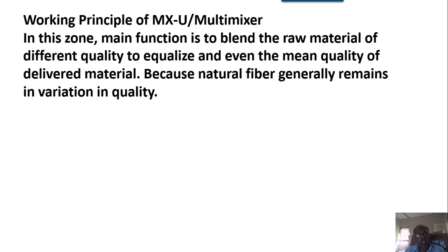So what kind of arrangements, the number of chambers, the input speed, the dropping of the material in a given particular chamber at a given time, and the traverse speed of the bottom conveyor, and then further beating of that, and delivery speed, they all govern how much a single tuft gets the time to mingle with the other tufts. This is the basic of this functionality.